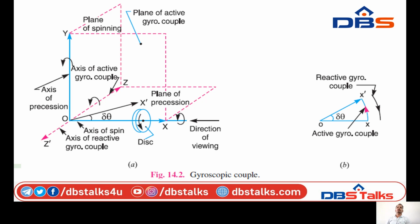In other words, the axis of spin is said to be rotating or precessing about the axis OY, which is perpendicular to both the axes OX and OZ. So the axis of this active gyroscopic couple is along OY, which is perpendicular to both axes OX and OZ.